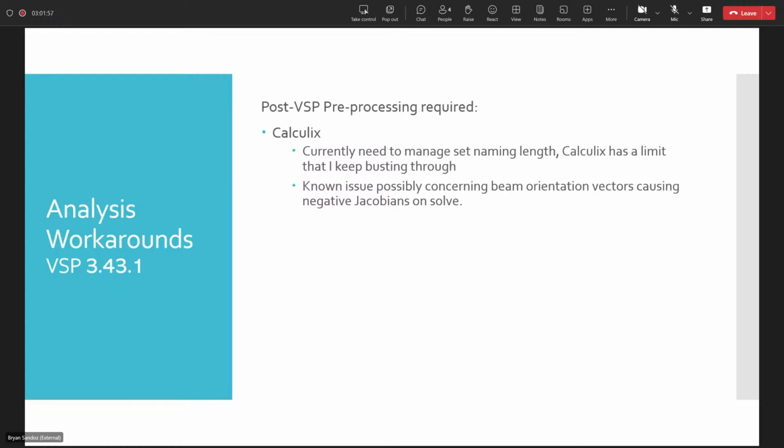In some cases, even if you set your wing assembly to be W and your fuselage to be F and your ribs to be R, it still gets long enough that it doesn't work. So I have migrated more to the MyStran and Nastran approach and left Calculix a little to the side in my work, which means we haven't addressed that.